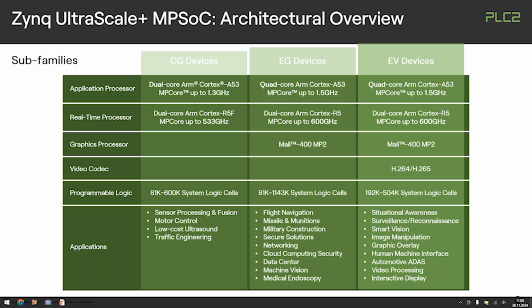So one of the good things that I said is really that the architecture of these elements is all the same. So the way that these devices are starting up, for example, out of reset, is always the same. And you can get control in a very similar way of all of these designs. The important thing to know, I didn't mention that before, is that the hard IP, the PS part, is the one thing that governs the wake up of the device. So you will have to provide your very first non-volatile memory, your very first design contribution, to that part of the device for it to access and to configure the complete downstream. So that's the concept of these devices.